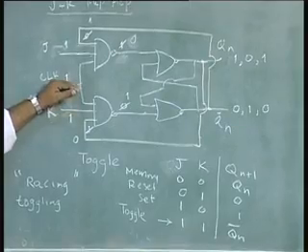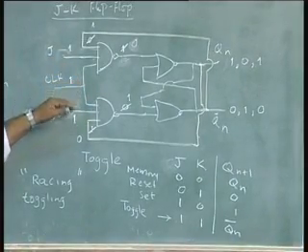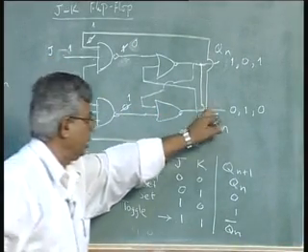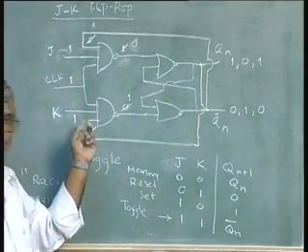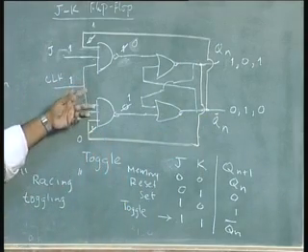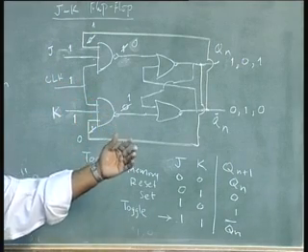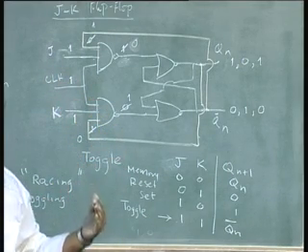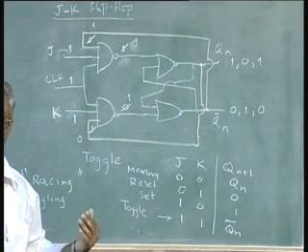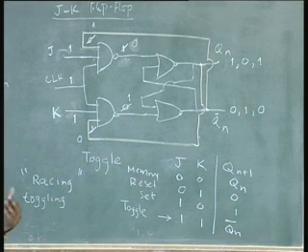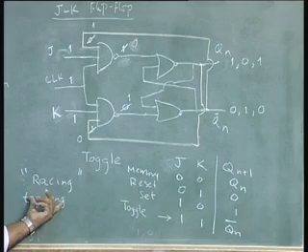So, if you put a clock high, put a set of inputs and let the output change, and by the time the outputs propagate back into the input the clock is already removed, toggling cannot happen. That means I need to operate with a very, very high clock, which is not possible and also not required. So, I should have some other way of controlling the toggle.